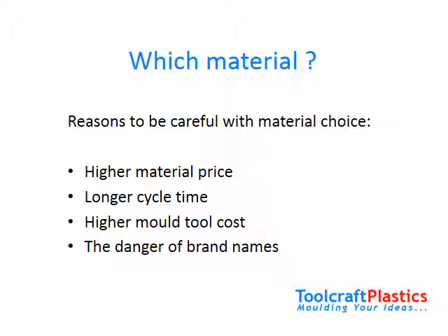What you may not have realized is that the polymer choice can also affect the cost of the injection molding tool. Some materials can only be molded in a steel tool, which is more expensive than an aluminium alloy tool. And the properties of certain materials may require more runners to ensure correct mold fill, which will also drive up the cost.